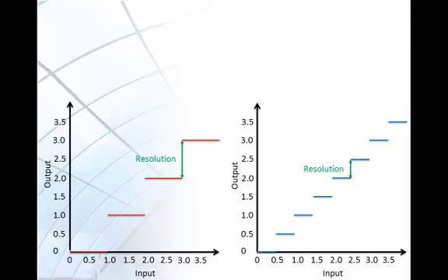On the blue graph, which is representing a sensor with higher resolution, a smaller change in input triggers a change in output value. The lower resolution sensor does not have as much detail. With a higher resolution sensor, it is possible to get a more detailed measurement. The high-resolution sensor on the right can register a 0.5 increment change in input, while the lower resolution sensor on the left can at best register a 1 increment change in input.